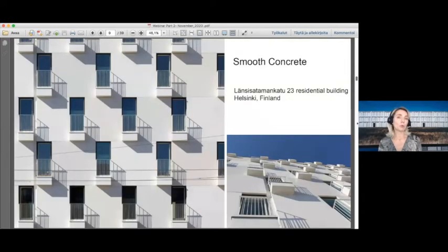This smooth membrane is mostly used when you have a white cement. You can also use it with a gray cement or with pigmented, but this surface is so perfect, so it's very unforgiving. Whatever little color difference in tone would show. So that's why it's preferable that you would use it with just a crisp white concrete. Becomes very, very nice, as you can see.